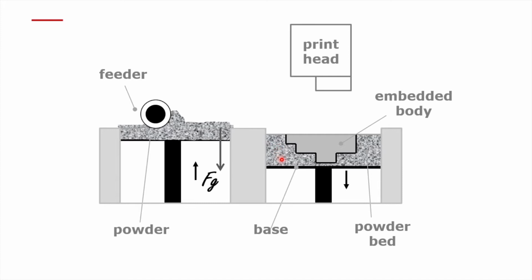So coming to one of the major problems of powder-based additive manufacturing for ceramics: when you use a dry powder, the packing density of the powder bed is not very high. And the reason is quite obvious. There's only one force acting to consolidate the powder, the gravitational force. You may activate the powder by some shaker or roller, but the gravitational force scales with the volume of the particles.